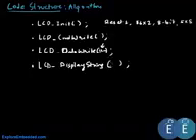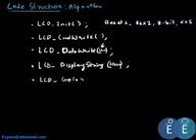It takes a string or string pointer as input. So if you pass a string, it displays the string on the lcd. Then there are other commands like lcd go to xy. This sets the position on the lcd. There are two inputs to it. The first is the line. If it is 0, it is line 0. If it is 1, it is line 1 on the lcd. So this is x and this is y. y is the cursor position.